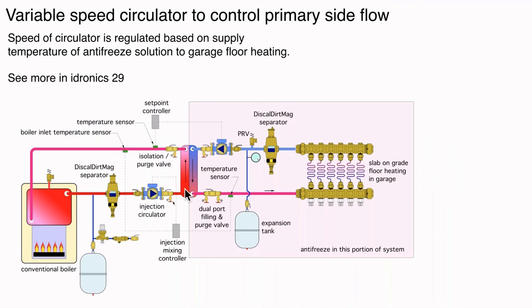Actually, one of those schematics, here's a variable speed pump controlling flow rate. It's not controlling the delta T across the heat exchanger. It's controlling the supply temperature on our load. I don't see, quite honestly, that the delta T control concept has as much merit as actually watching the supply water temperature. That is really what's going to determine whether your heating system is getting adequate heat transfer.